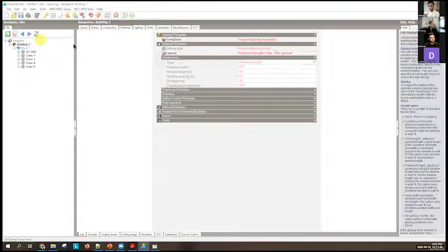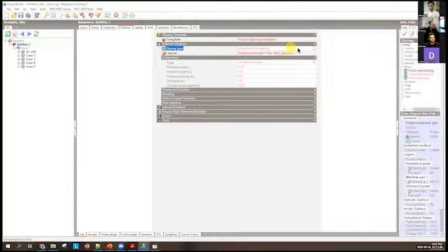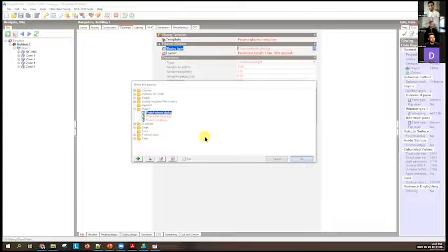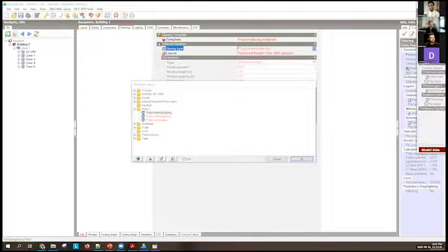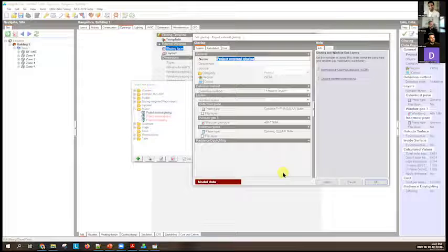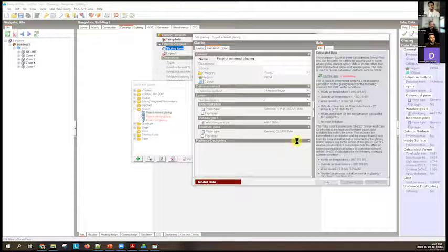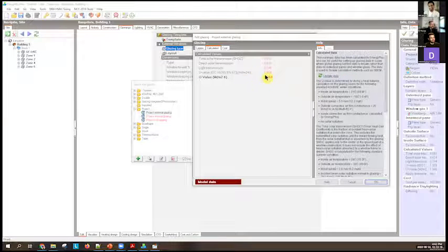So the way windows work, again, there's something called a glazing type, which is where the performance of the window is described. And the performance of the window, if you know your building physics, is really, you're looking at 3 values, okay? And those three values are the U value, the solar heat gain coefficient, and the light transmission. These are the three performance numbers you want.